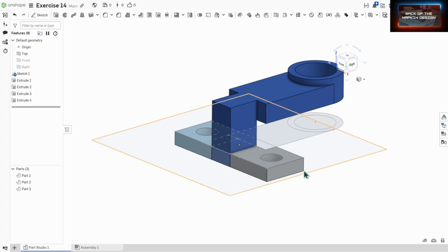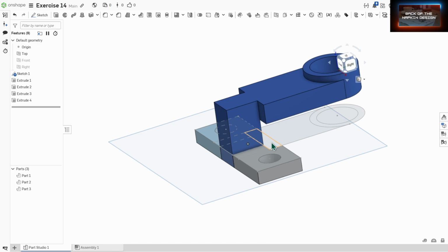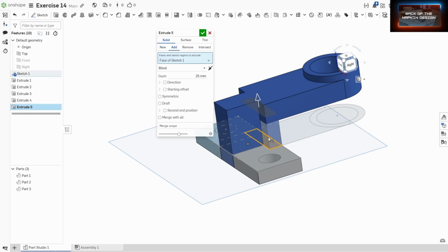That's good. Now we're going to build this one. We're going to make another one and go down 10 millimeters. So let's extrude this here, opposite way. 10. Okay, and it's a new body. We can do add, and we can say merge with this guy if we want to. If you don't like that, we could do a union afterwards.